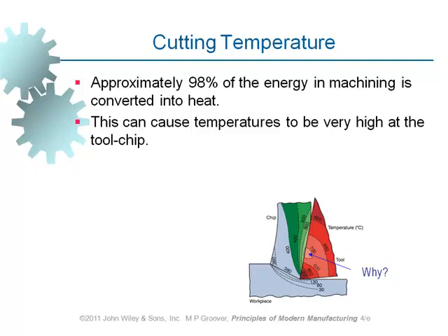The reason is that friction occurs between these two. The friction of the chip and the cutting tool, which produces a lot of heat energy, is between these two pieces, and that one is not involved, which is good for us. Because this is the one which decides what is left. The geometry which is produced is this one. And that one receives minimum heat energy, so the expansion will be minimized.